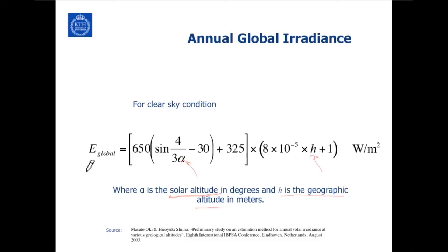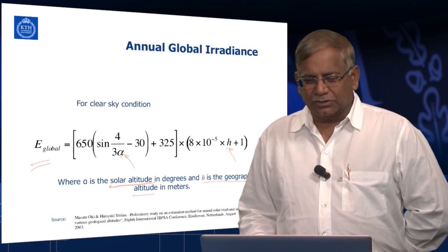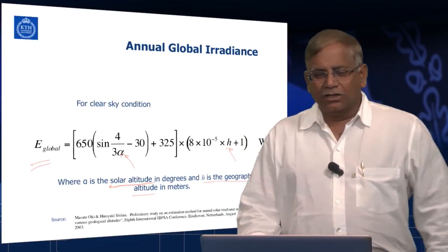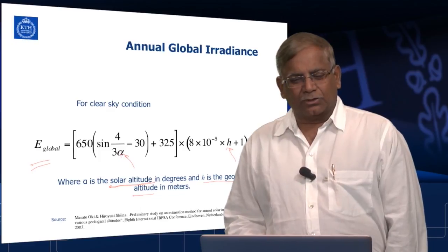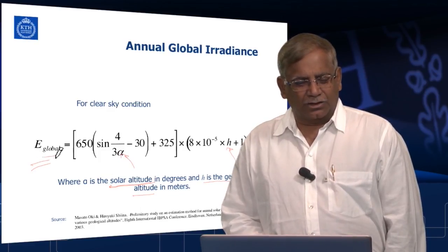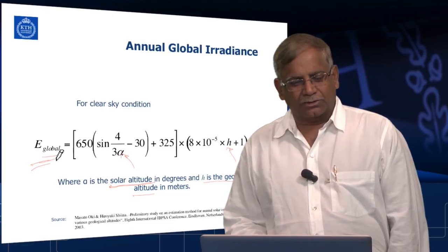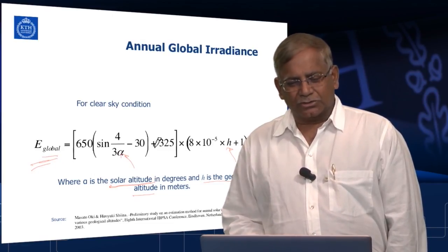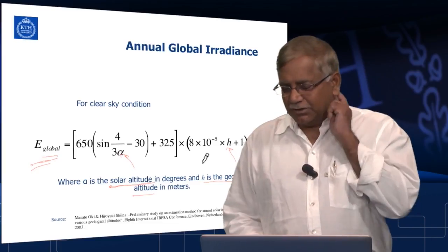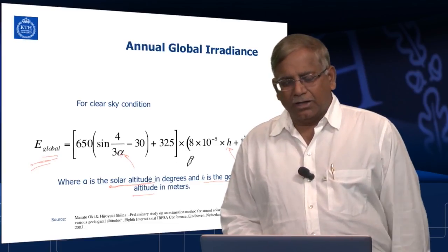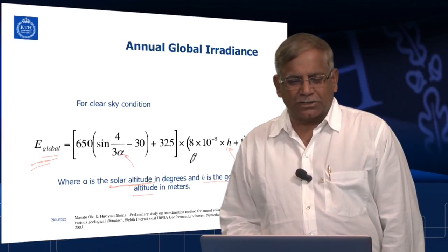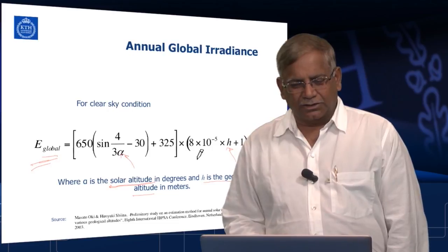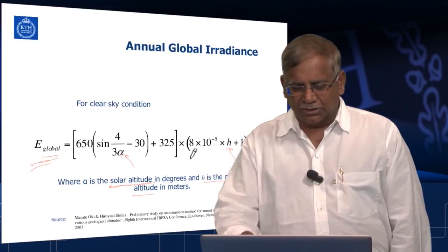If you know that, you can calculate insolation by using typically this formula, and this will give you watts per meter square, integrated over time per day or per year, and then you get the total insolation. And this is the global part, which has both the direct normal insolation and the diffuse insolation. So this is a simple way to calculate, but in most locations people have already measured this, either through satellites or from ground based measurements, and these are tabulated for any location around the globe.